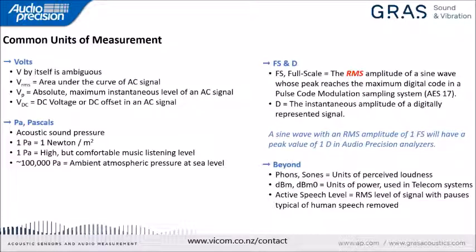So as we talk about audio measurements, the most fundamental thing of all will be the units in which those measurements are expressed. So let's talk about some of the most common units and some of the most common gotchas or caveats to be aware of in those units. Depending on where you're coming to test and measurement from, probably the most common unit is either going to be volts or pascals. Starting with volts, the first thing I'd like to note is V by itself is ambiguous.